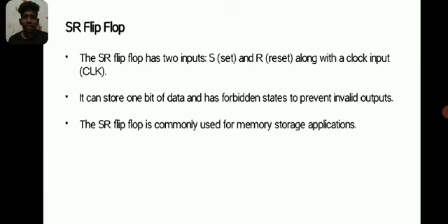SR flip-flop. The SR flip-flop has two inputs, S (set) and R (reset), along with a clock input CLK. It can store one bit of data and has forbidden states to prevent invalid outputs. The SR flip-flop is commonly used for memory storage applications.